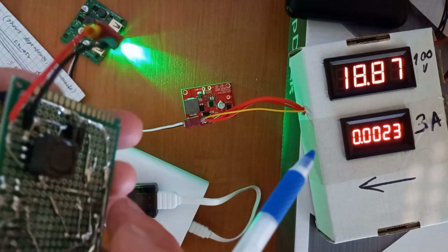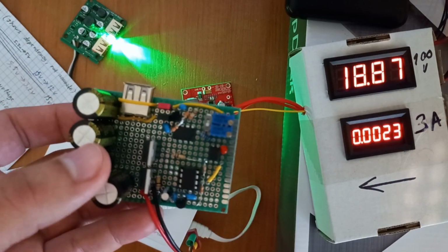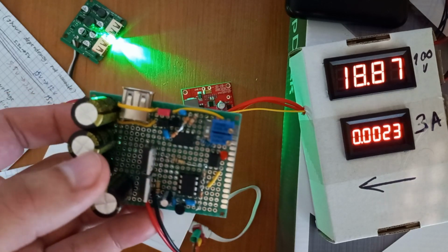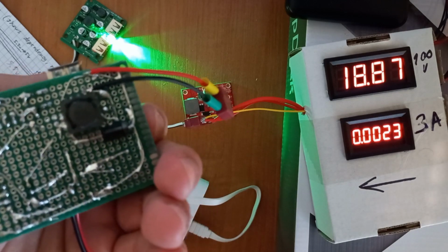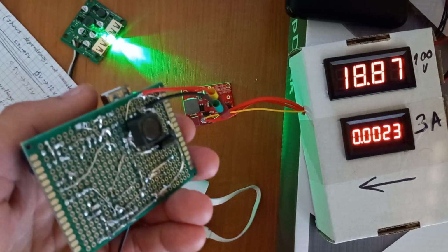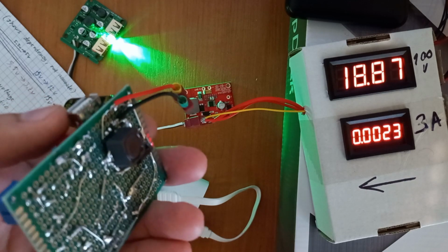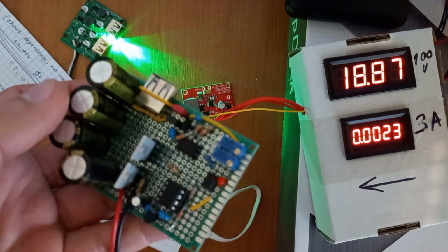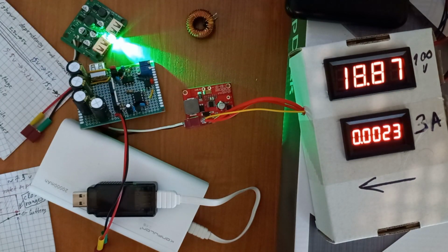This exact prototype is fine for a 50 watt 18 volt panel, for 12 volt 4 amps output-ish. The inductor is the limiter here, because it's rated for 5 amps, and I actually have no idea where you can find power inductors in Ukraine. For higher currents, there should be a stronger inductor and a radiator on the MOSFETs. Note that after reaching the inductor's limit, you can still receive bigger current, but it will work inefficiently and stress other components.